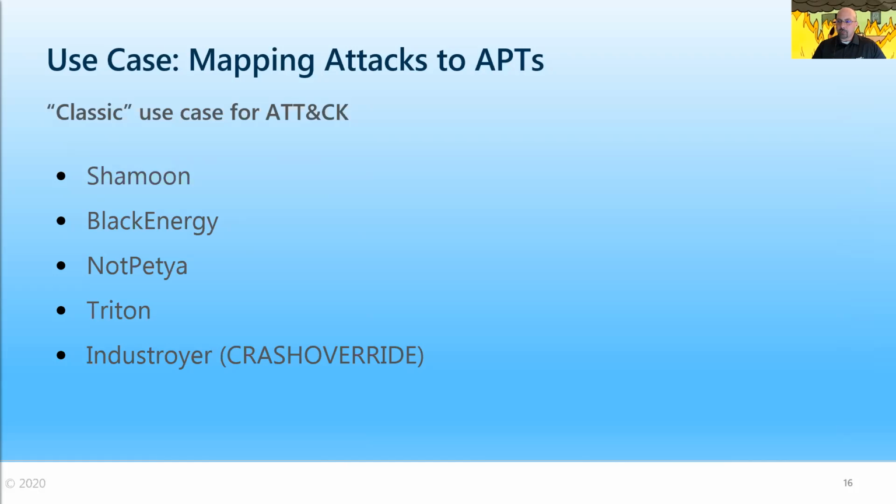That's some modular malware that was designed to affect specifically targeted substations using serial communications, IEC 104, IEC 61850, and OPC protocols. So that one was specifically targeted to the protocols that are used in Ukrainian substations. It could easily be adapted to DNP3, which is used a lot in the United States. So this type of malware is something that may be seen in the future, targeted towards some of the United States substations.